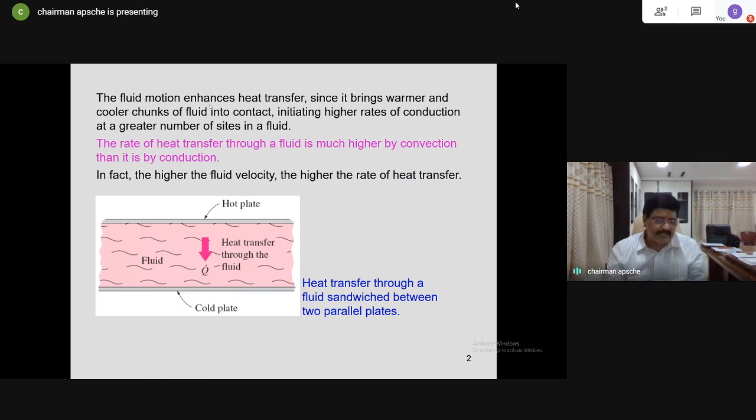If there are opposing forces to the natural motion of the fluid, particularly in natural convection, heat transfer coefficient will be very, very less, or convection heat transfer will be less. And such fluids with minimum resistance, with all favorable conditions like low specific heat, density decreasing very readily with the temperature, and viscosity very low, these molecules, such fluids, they rigorously participate in convection heat transfer. The rates of convection heat transfer are also very, very high.